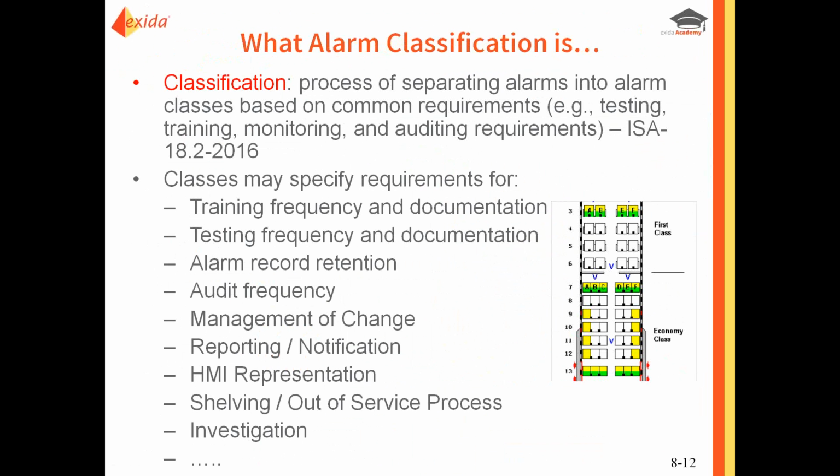What is classification used for? How does it differentiate? We already talked about testing, so training as well would be another set of requirements that might be different depending upon the class of an alarm. How long the alarm information is retained in history, the frequency of auditing, management of change. So there might be much more rigorous process required for more critical alarms, for example, than those that are just your